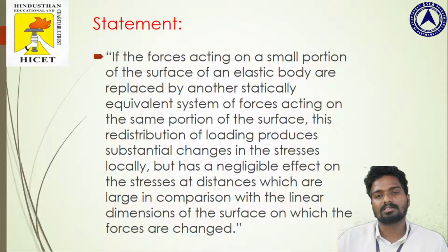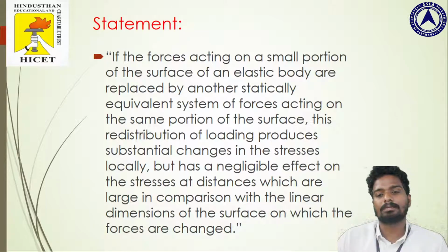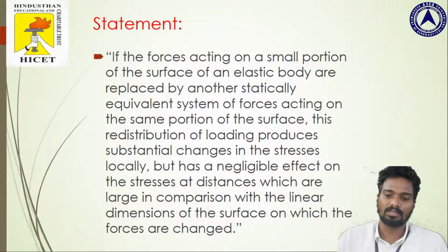The statement says that if the forces acting on a small portion of the surface of an elastic body are replaced by another statically equivalent system of forces acting on the same portion of the surface, this redistribution of loading produces substantial changes in the stresses locally, but has a negligible effect on the stresses at distances which are large in comparison with the linear dimensions of the surface on which the forces are acting.